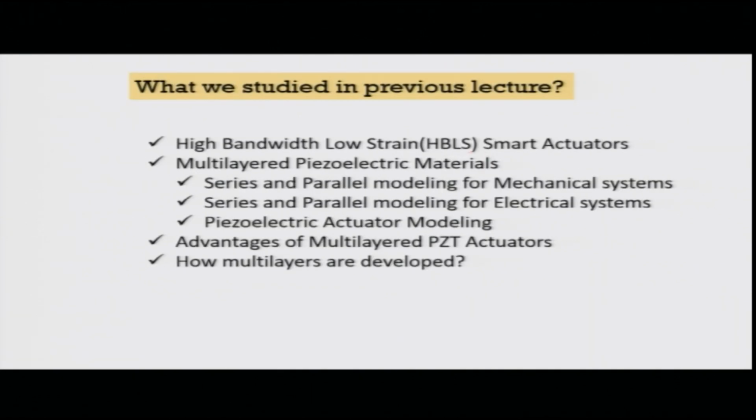we talked about these HBLS, high bandwidth low strain smart actuators. We also discussed that if you have to develop such actuators, how you have to intelligently employ multi-layered piezoelectric material, and there are so many issues there. For example, the series and parallel modeling of mechanical systems, similarly series and parallel modeling of electrical systems, and then the piezoelectric actuator modeling out of it. Then we also talked about the advantages, why we should do it, and how you can form such multi-layers.